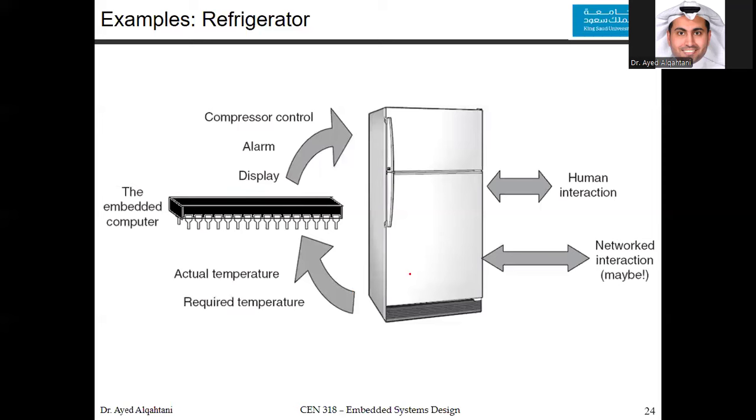So let's look at this here. If you say that the frequency of oscillation is equal to 80 megahertz, and you take the reciprocal of this value, which is 1 over 80 megahertz, you'll end up with 12.5 nanoseconds, which is the machine cycle, or the TOSC.